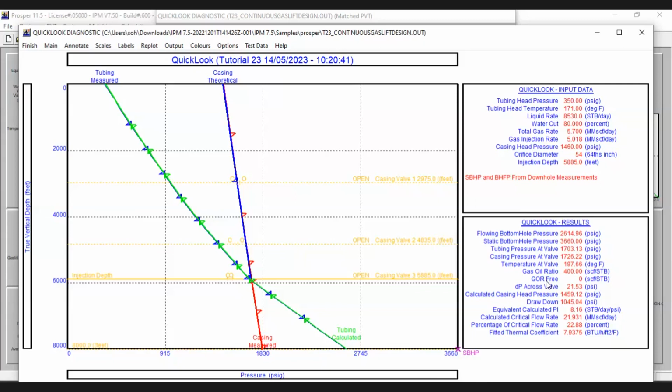It means that every time a test is conducted, you need to look at the test and check if it is looking good in terms of PVT, formation volume factor, and viscosity. All the things need to be checked and QC'd, and after that you need to make sure that the model is verified. Without verification and validation of the model, you cannot get future response and management decisions for your well.